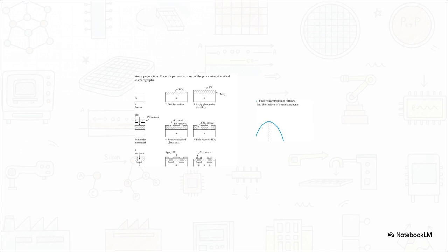Because diffusion relies on a concentration gradient and thermodynamics, the impurity atoms move into the silicon to create this beautifully graded, nonlinear curve. This specific mathematical grading is critical. It determines the precise width of the depletion region, which in turn directly controls the breakdown voltage and capacitance of the junction. We are literally using physical manufacturing to dictate pure functional physics.